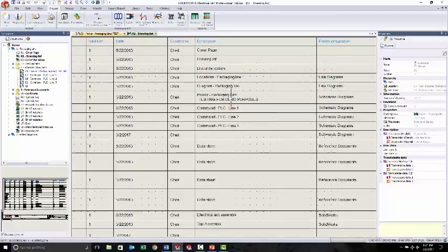All right, so I'm going to look at that drawing list now. The drawing list now breaks it apart and gives you 2 lines of text, where before it put that pipe symbol in there. So it automatically is adhering to that same style. Address, comments, and a PLC. Address, comments, and CAN. Do you do that there also? Address, comments, descriptions for your I/O points. Anywhere that you use multiple attributes, this will now recognize that.